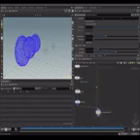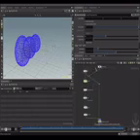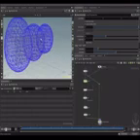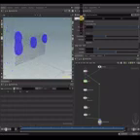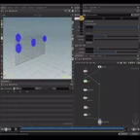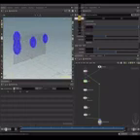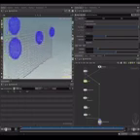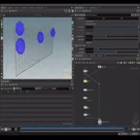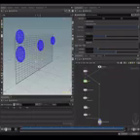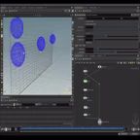Let's set the box as template. And if I lower the impact radius, something like this, this node allows us to scatter some points within these spheres. And it's cool because we can decide where to place points. We can place them at the surface, at the exterior or interior of these spheres.